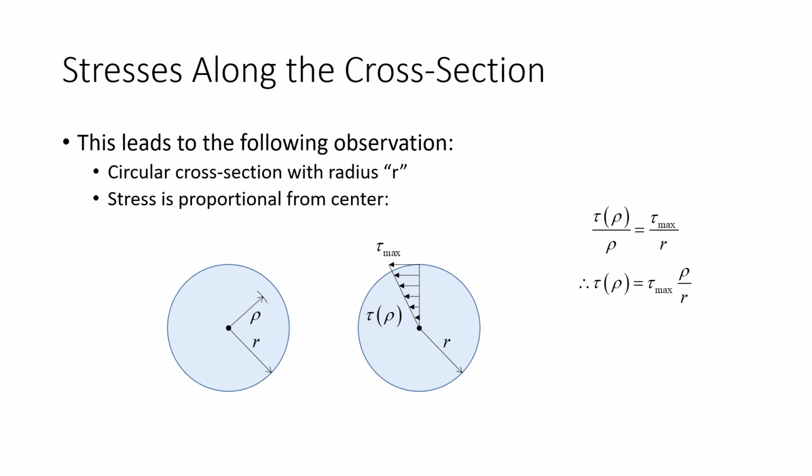See, that's a little bit different, okay? And maybe that's another unique aspect of torsion that didn't exist with axial loads. If you take a bar and you yank on it, you get sigma equals P over A. But that's the case everywhere, right? So for example, if this was a circular bar and I yank on it, I get sigma equals P over A, and that stress is here, and here, and here, and here.